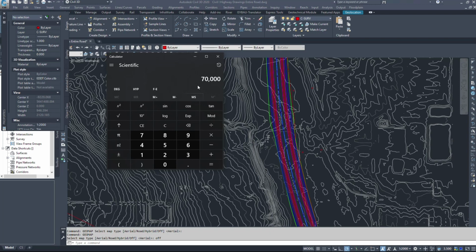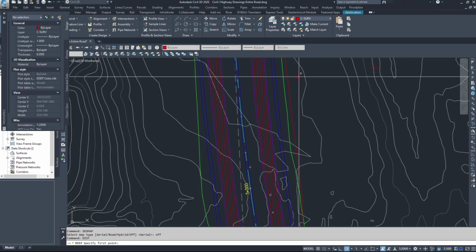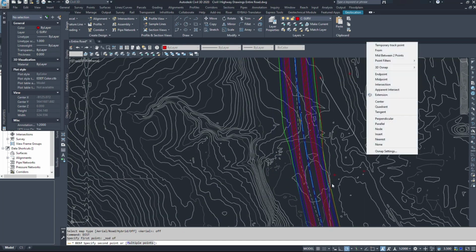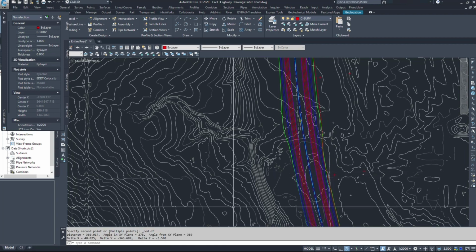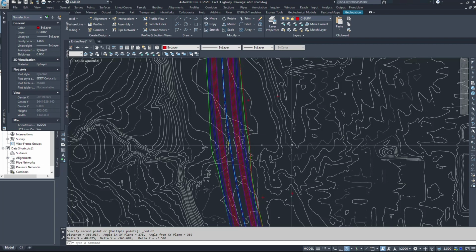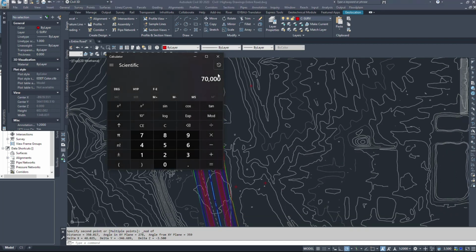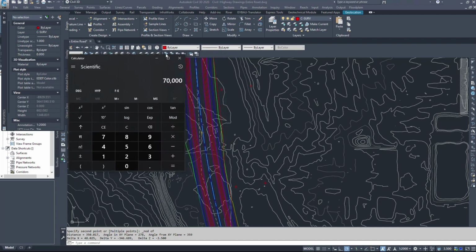Again, it's all going to depend on the space, the area. I've got an approximate shape here. It's 100 by 350, I believe. Just measure the distance between these two. 350 meters. Now, I've marked this out tentatively so I know where to place the pond. But I'm going to go with 100 by 350, and we're going to make it 2.5 meters deep, and that should account for our 83,000 cubic meters that we need to store.